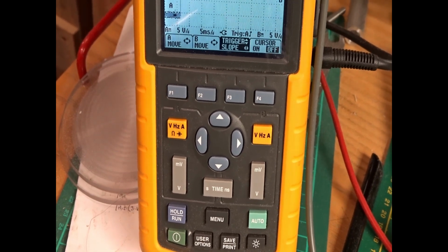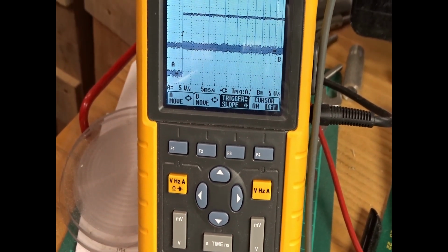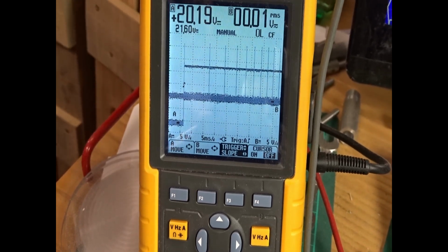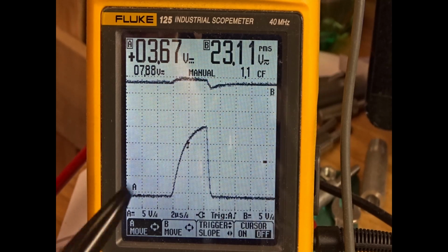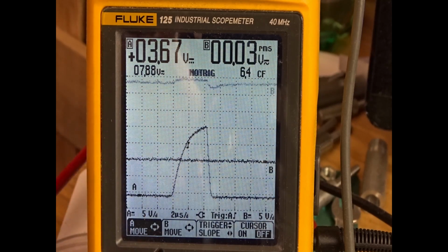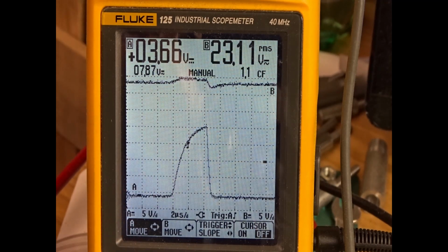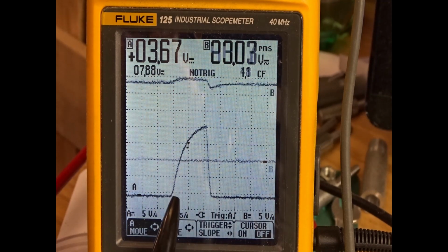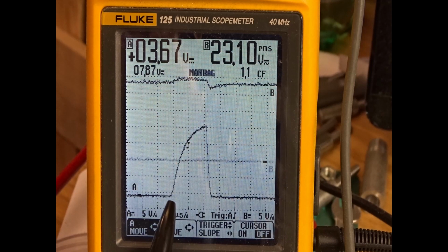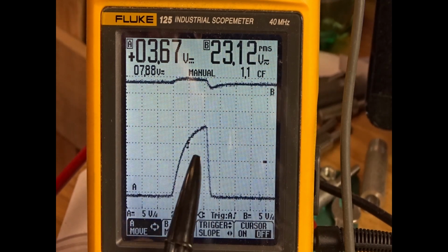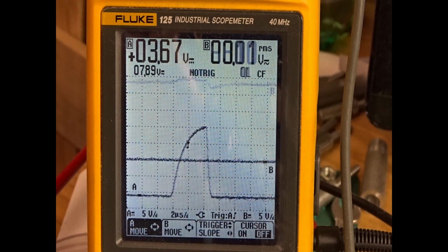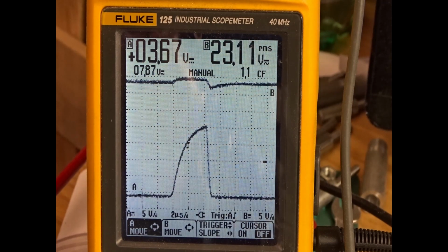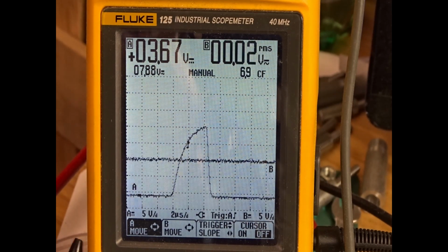There's the buttons on the scope. Okay, B is the direction now, A is the pulse, and that's set at 2 microseconds. So 4 microseconds, but by the time it gets up there enough to turn on the opto isolator, I don't think we're getting the full 4.